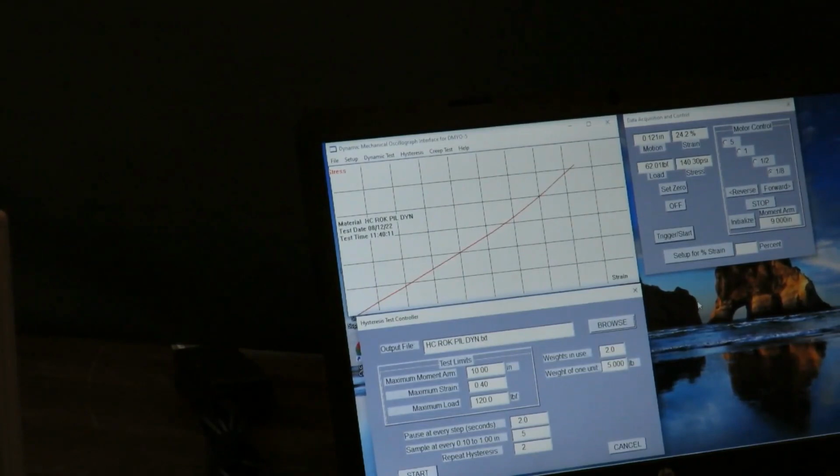What's important in hysteresis is loss of energy. As the specimen experiences compression forces, when the forces are reversed, some of the energy is wasted in the viscous component, and the elastic component, of course, stays the same. However, it depends on the filler structure, the agglomerate, mixing, and cross-linking structure of the final component, and how it behaves once it comes out of a mold.